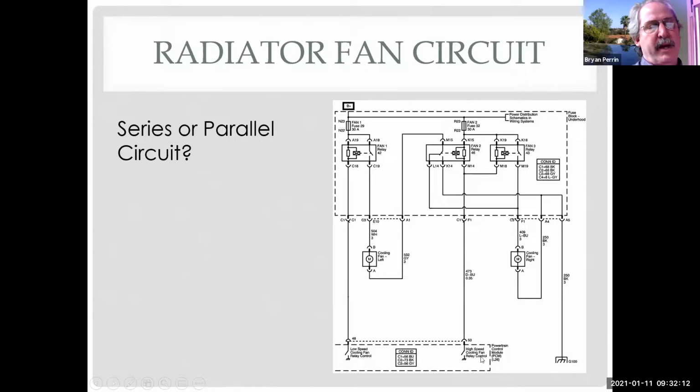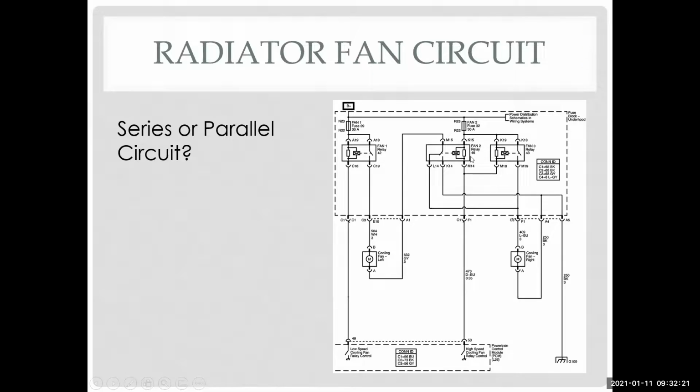And so this is my high-speed cooling fan. So the computer, again, is going to come up, and what it's doing here is actually turning this relay on and the radiator fan relay on, both at the same time.